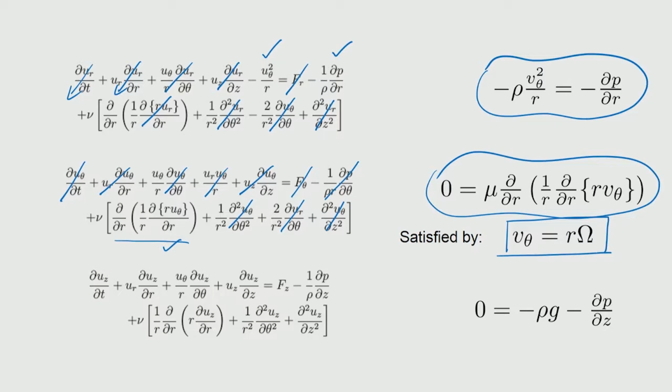In the case of the z direction also, the velocities are not there, and so those terms go away, and you see that this must be the body force, which is basically the gravity term, and this must be the pressure variation because of the z direction having different heights of the liquid as you go along the r. Okay. So, you have this equation.